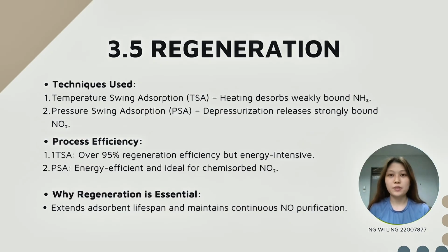To extend adsorbent lifespan and maintain efficiency, tailored regeneration methods are applied. For natural zeolites, which we use to remove ammonia, we use thermal desorption to release adsorbed molecules with moderate heat. For ion exchange zeolites, which adsorb nitrogen dioxide, chemical regeneration is required to break strong bonds and restore adsorption capacity. These methods reduce operational costs, enhance sustainability, and ensure long-term system performance.